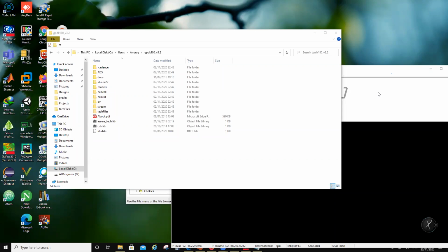There is something called the Courant factor. The Courant factor is basically a dispersion when you go diagonally in a cell, right? So these things are there in a 3D simulator. FDTD is a 3D simulator. FEM is a 3D simulator. Method of moment is always a 2D simulator with some fudging. And Cadence has a method of moments, but it is not Momentum.